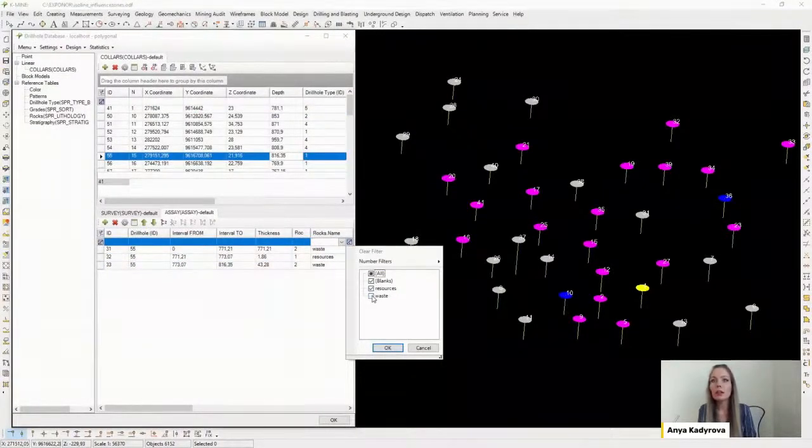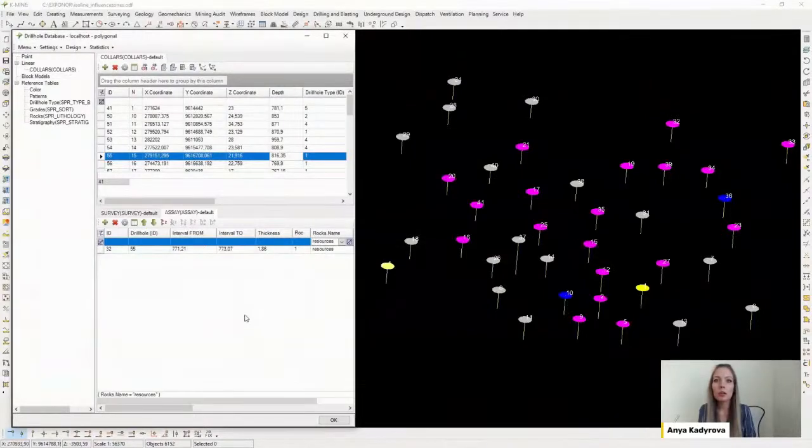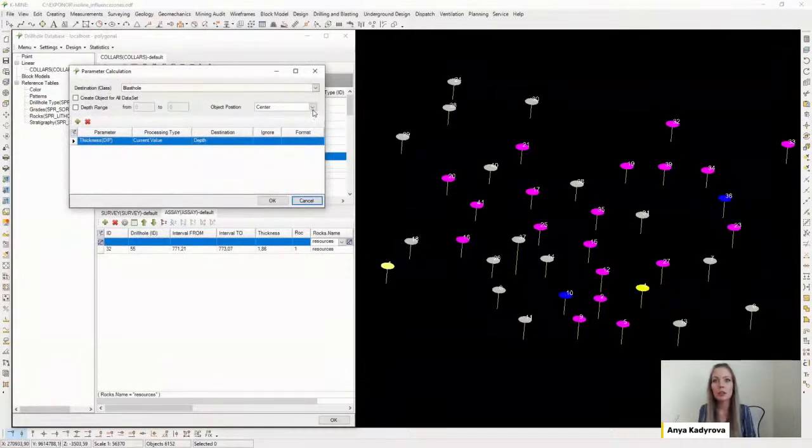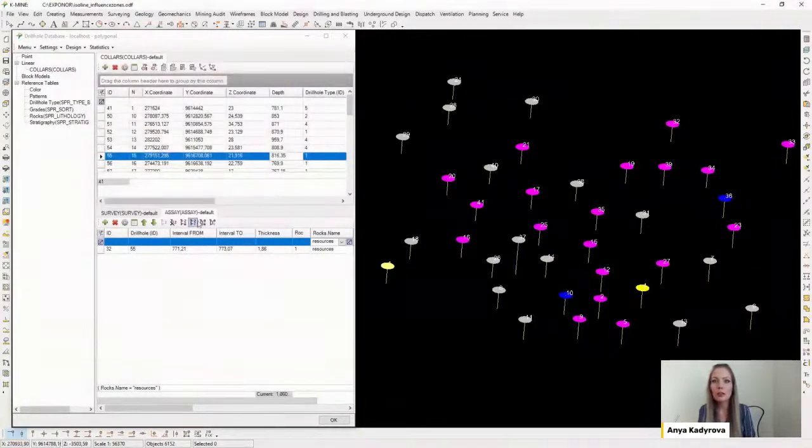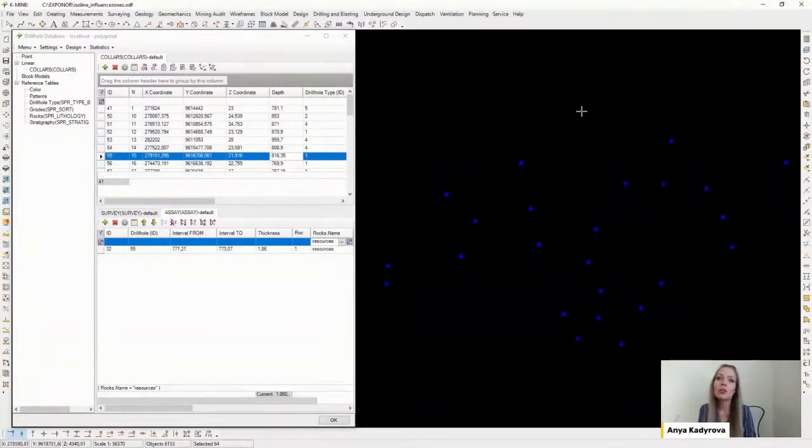So you have simple grade tonnage calculations using polygonal outlines. Just before constructing influence zones, create graphic objects with calculated thickness parameters or grade values. Using the set of Thiessen polygons with calculated average thickness, you can calculate zone area and volumes by influence zones. Knowing the value of density, you can also get a report on the resource tonnage.